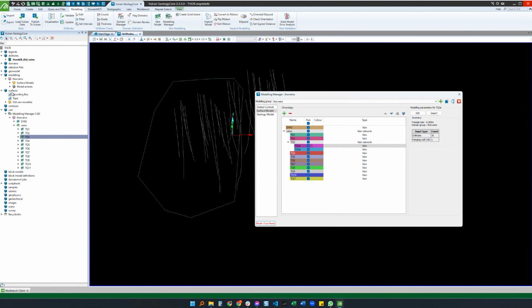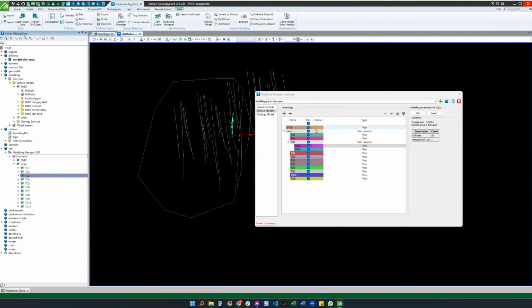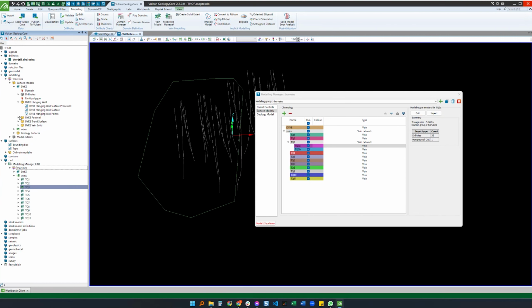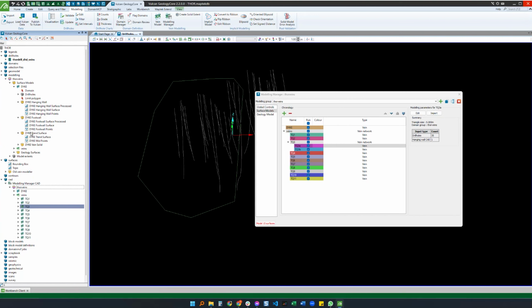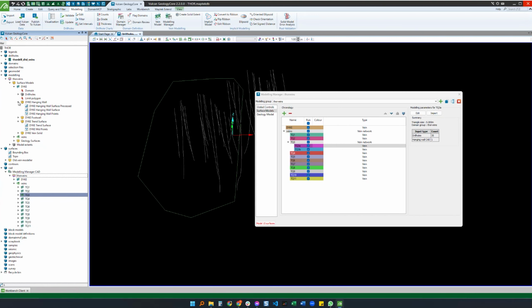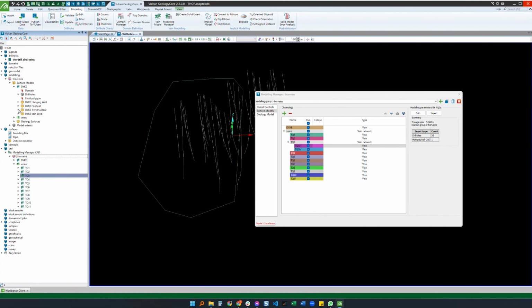Right, so now that that's run, in here we've got this surface models container which matches up for this surface model, right? And each of my items, so for my dike, which is a vein, it's got all the outputs that you'd get from the vein modeler, right? So the points, the original surface, and then the process surface. So you can go through and see if you've got any problems that have happened with any of your models, you can go and investigate and see what might be going on.